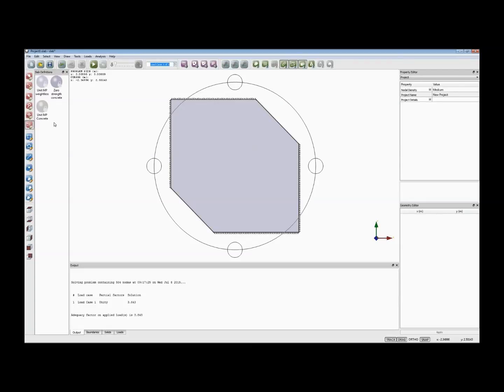define different material properties for each section of your slab, and you apply them individually. So you put new MP values and unit weights and slab thicknesses there, and we call that a slab definition.